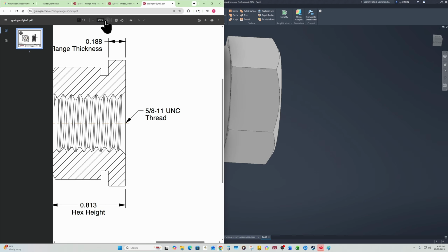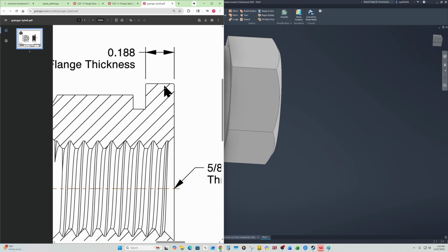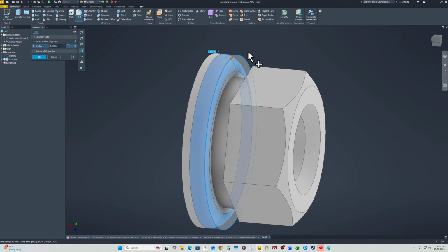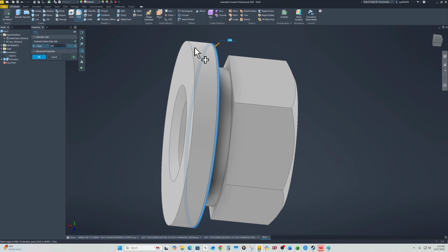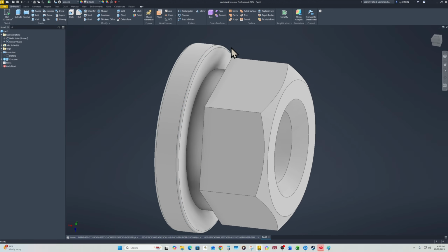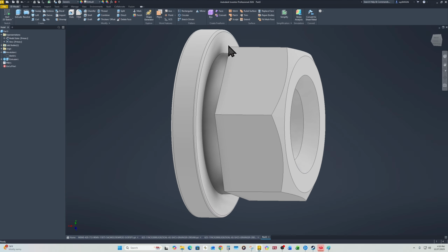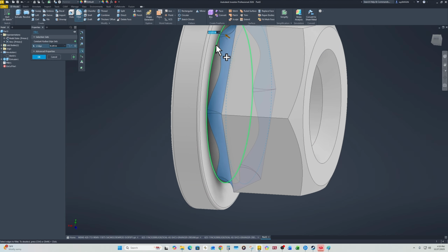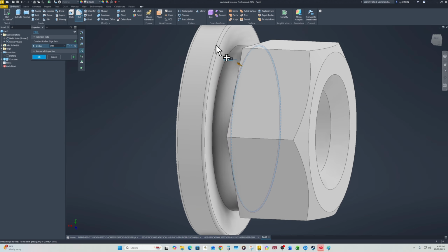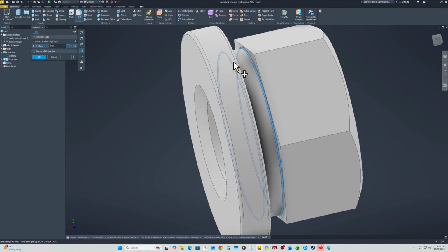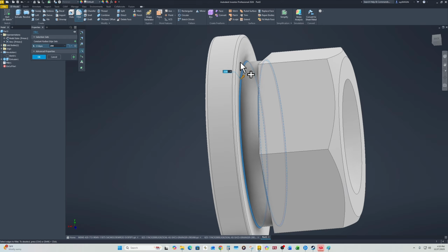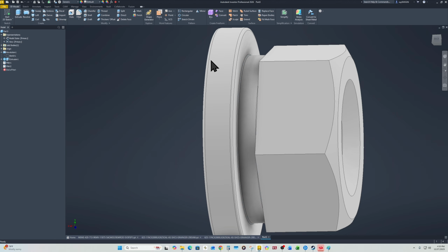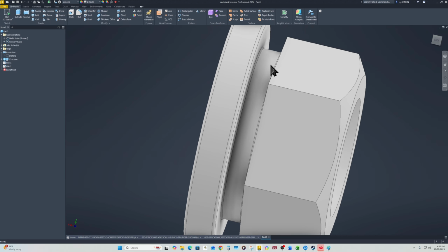I guess maybe it looks like a radius, so I'll give it a radius of 0.016, something really small. That's probably not right, but whatever. And we can only assume it's going to have a radius on the insert, so I'm going to use some radius that I know it would be, and the radius of the insert would be 0.008 on the corner radius. So that's technically to me what it would look like, if I were to do it.